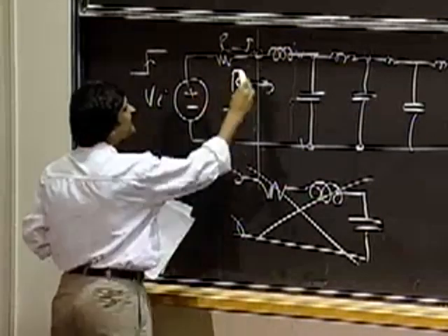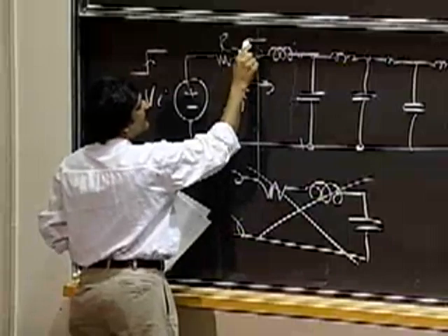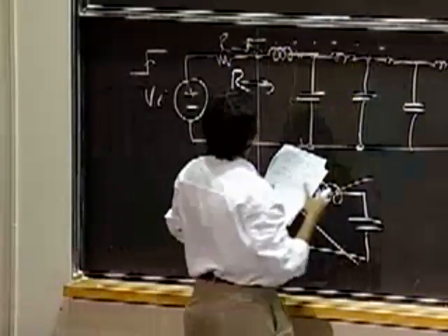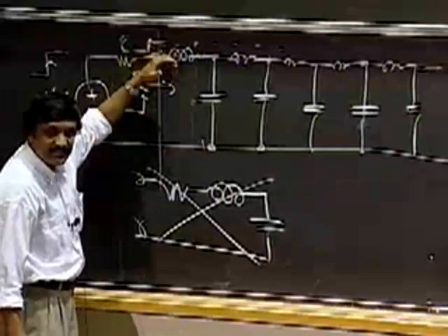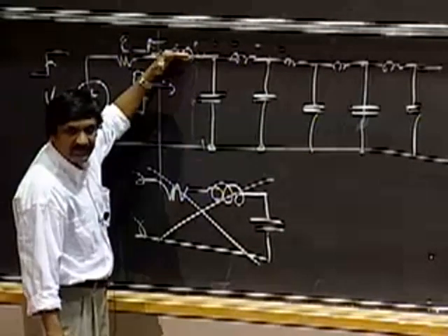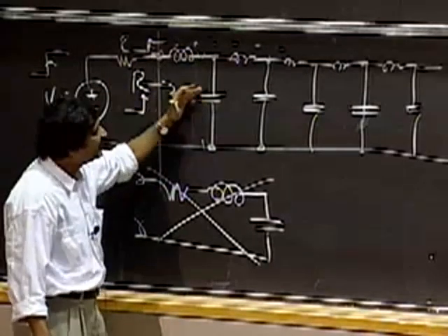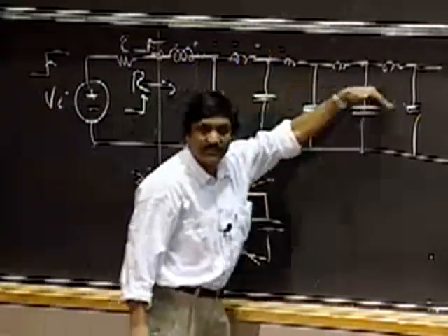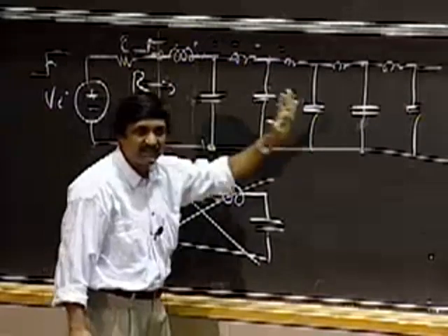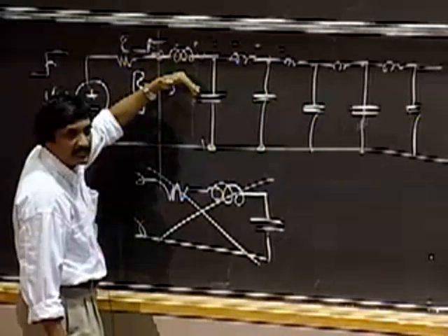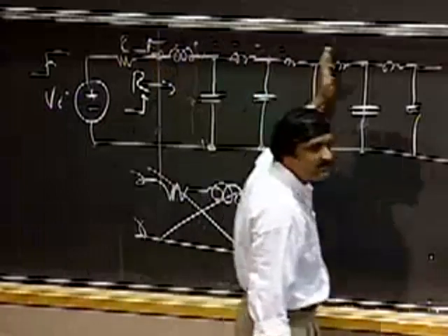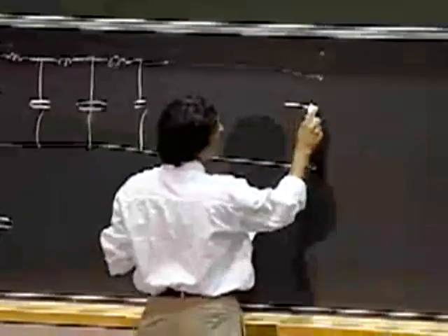Then what happens? Then this little pulse propagates down. What does it mean for a pulse of energy to propagate down? Well, I begin charging up the inductor, begin sending a current through the inductor, begin charging up the capacitor, so that's what I mean by saying that the pulse of energy goes down. It's a step that sends current through the inductor and charges up the capacitors, and that wave front moves out here and comes all the way here.